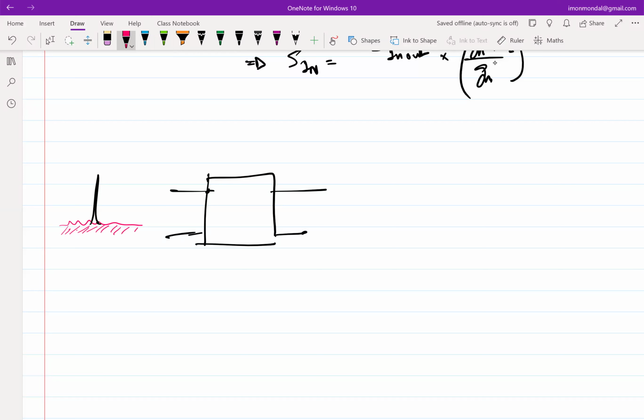You have a spectrum analyzer, you found this, right? This is, let's say, the picture of a spectrum analyzer. How would you know what is the signal to noise ratio of the input? Firstly, let's go with the signal. How do you know what is the signal strength? Yeah, the tone that is standing up, the power of that, you just read it off, whatever you get, right? So the strength of this is signal.